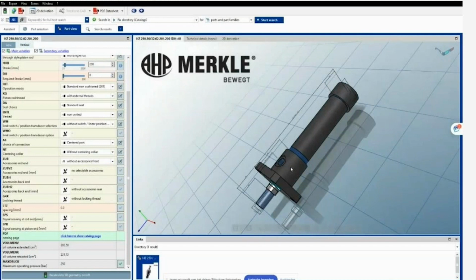For maybe plastic injection mold, it's not necessary to have a hardened piston, but having a hardened piston will assure that you will never have scratches on the piston that then will also damage your seals.